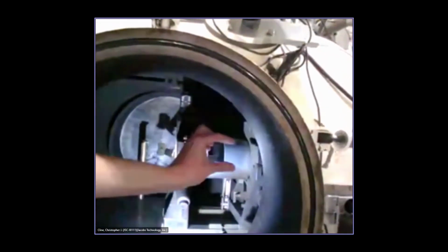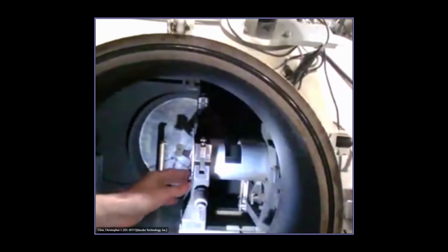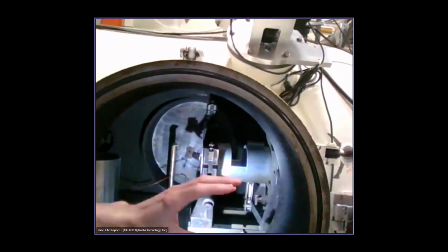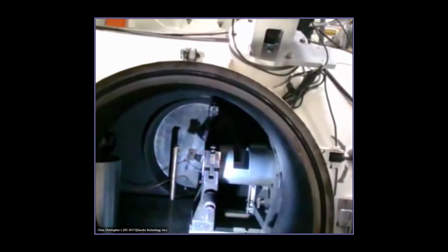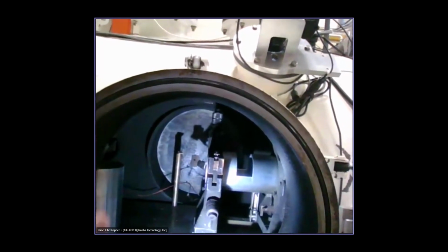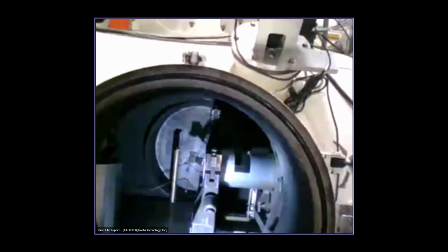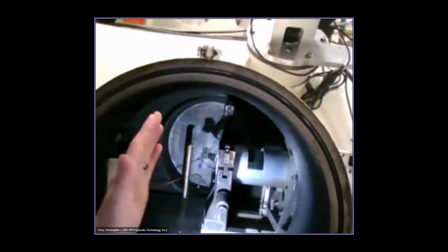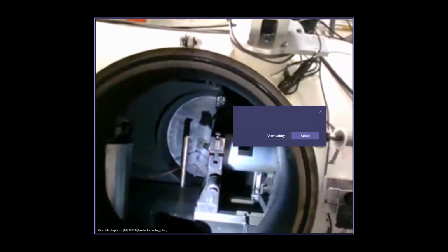When the projectile is inside that window, that's when we snap our picture. We do that to make sure we can look at the orientation of the sample in space right before it impacts, because the physics involved in determining the pressure that's achieved relies on a perfectly planar impact. So we need the tilt of that projectile to be very little. We want it to be as straight up and down as possible.